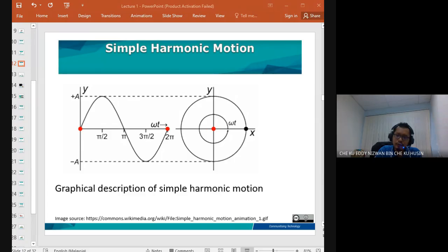This is what we call vortex shedding: when the wind flows towards the bridge, it can create vortices, which create harmonic excitation. This is due to the structural weakness, because the vortex shedding coincided with one of its natural frequencies.